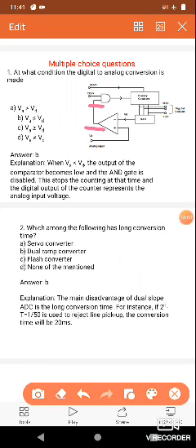AND gate, a binary counter, and a digital to analog converter output. This total circuit represents question number 1, and it is a counter type ADC. We can say this because the analog input is applied to the comparator type op amp, at its non-inverting terminal, and the DAC output is connected to the inverting terminal of the op amp.